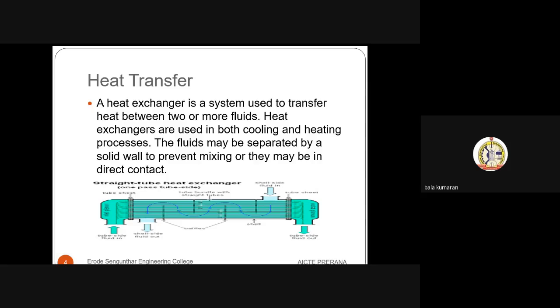It will be separated, and while the hot fluid passes through the tube and the cold fluid touches it, what happens? The hot fluid releases its heat, and the cold fluid absorbs the heat. This is known as a heat exchanger. There are many types of heat exchangers, classified by nature of the heat exchanging process, relative direction of fluid motions, design and constructional features, and physical states of fluids.